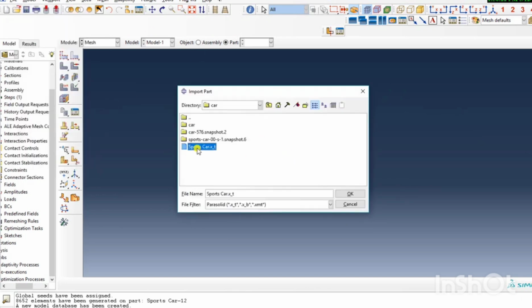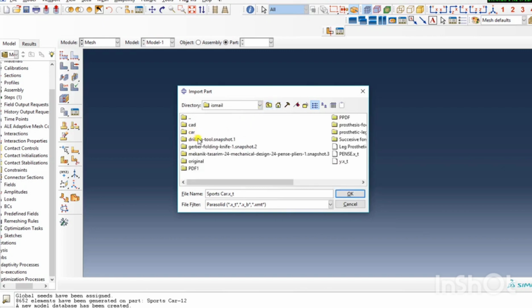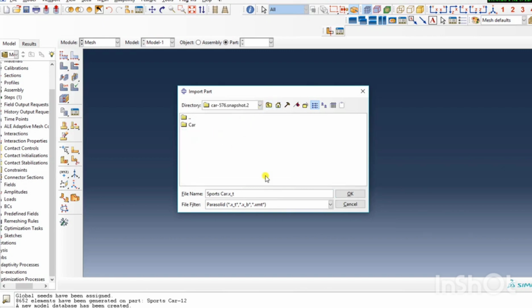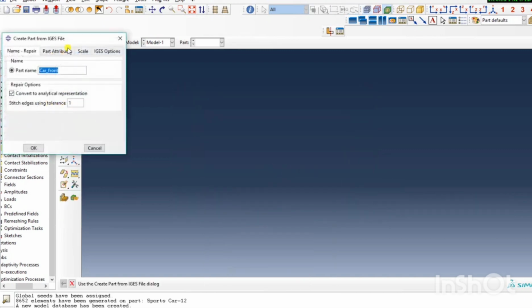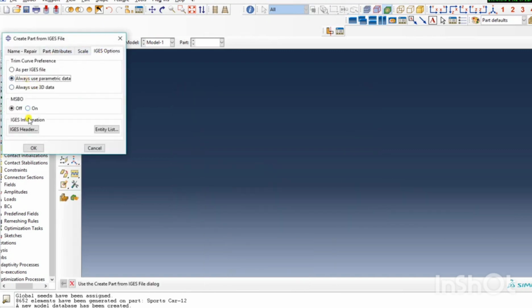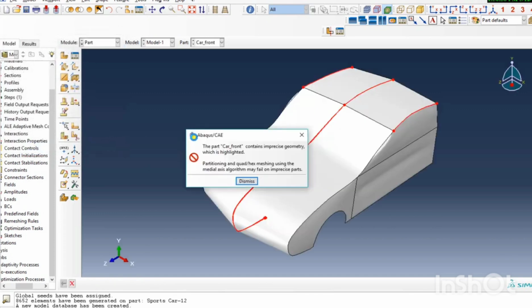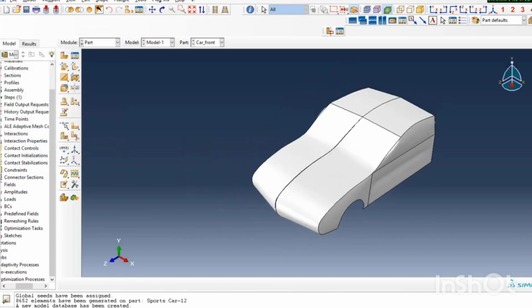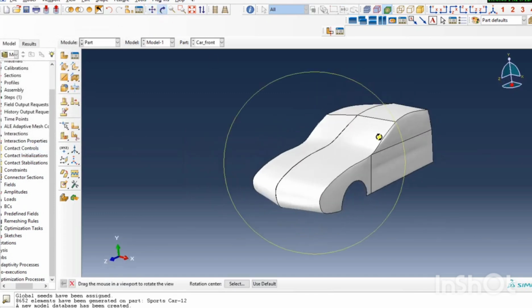Hello everyone. In this study, we are performing an explicit dynamic crash simulation of a thin-walled steel column using Abaqus. The objective is to evaluate progressive buckling, plastic deformation, and energy absorption characteristics under axial loading, which are very crucial in automotive crashworthiness design.